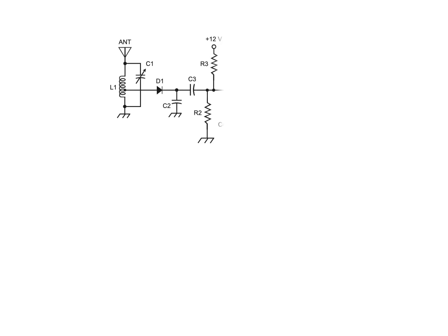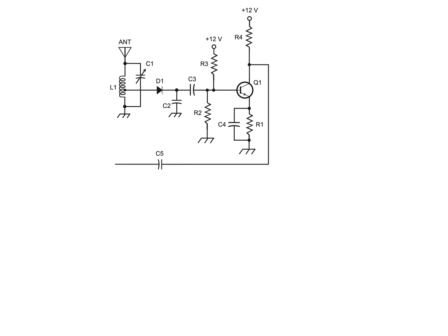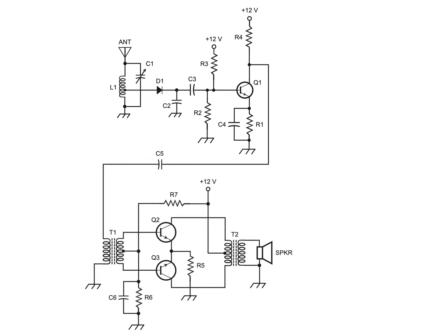Now if you combine the three circuits in cascade, one after the other, you get a complete amplitude modulation, AM, radio receiver that will produce decent sound from a loudspeaker. This slide shows the entire 3-transistor AM radio receiver in a single schematic diagram. Again, some of the component designators are changed from previous diagrams, so that they increase generally as you go from the original input at the antenna to the final output at the speaker. If you were to have seen this final circuit at the start, you might have experienced some major frustration. But now that you can see how the building blocks go together, you know that you don't have to choke down the whole burger in one gulp. So it's pretty simple after all, isn't it?